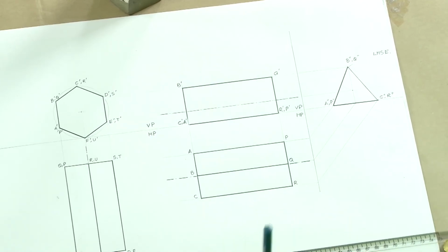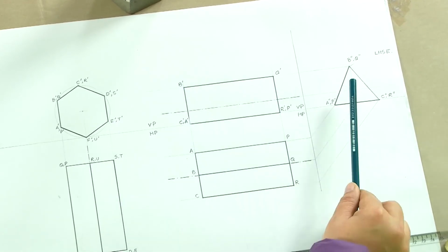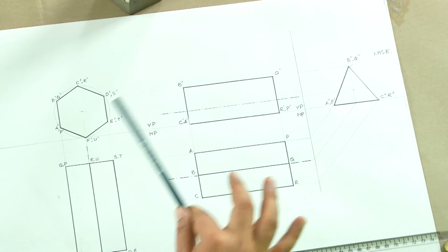Now here again, since we were drawing a prism, you are seeing that we are able to get only the rectangles, and the true shape of the base is seen in one of the reference planes. So I hope with this you are able to understand how to draw the basic orthographic projections of solids in simple positions, where the axis of the solid is either perpendicular or parallel to one of the reference planes, or it is parallel to both the reference planes and perpendicular to a side plane, which is an auxiliary plane. So this is about projections of simple solids in simple positions.